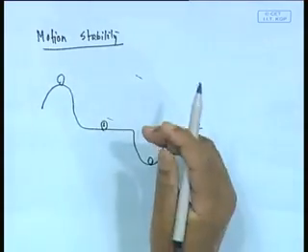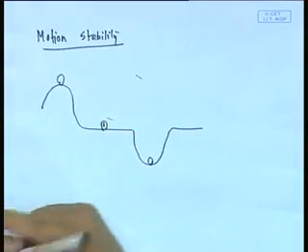In other words, a stable equilibrium means if I change the system from the initial state by some small amount, it comes back. This we talked about in terms of static stability. Now the same kind of concept applies for motion or directional stability. But remember, a ship is neutrally stable in the horizontal plane. So there are actually four kinds of course stability possible.